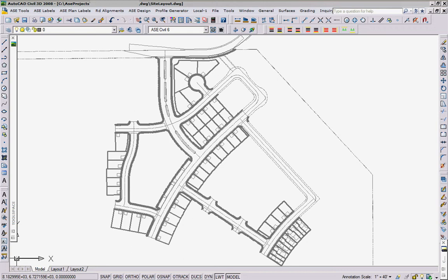If alignments will be defined using ASC, we recommend using the site layout as a control drawing. Keep in mind that use of ASC civil alignments is not required to use the remainder of the application. If you choose to use LDD or Civil 3D alignments instead, ASC Civil will automatically detect them, read their properties, and acquire any requested data from them, just as if they were created by ASC. You can also take advantage of the easy, fast creation and editing methods ASC Civil uses for alignment definitions, then click a button to upload them into the LDD or Civil 3D database afterwards if you like.